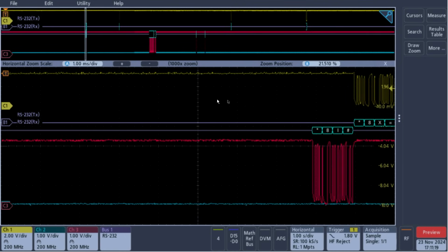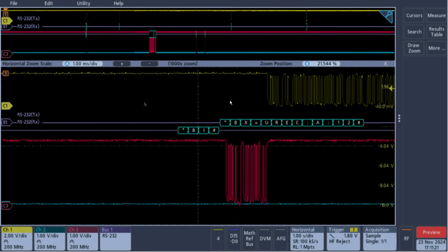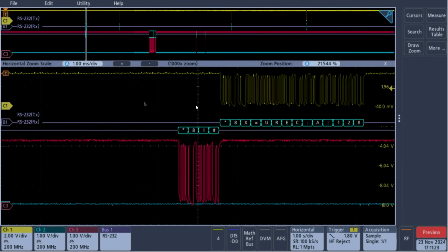After a few reboots of the console, I was also able to find the desired init commands for the expansion card. And what can I say? Even the name is transmitted as a plain text command. Great! This means I can fool the X32 into thinking it has any known expansion card, whether X-ADAT, X-USB, X-Live.